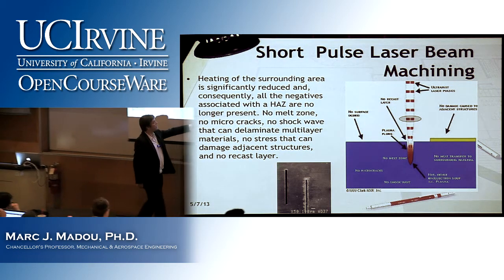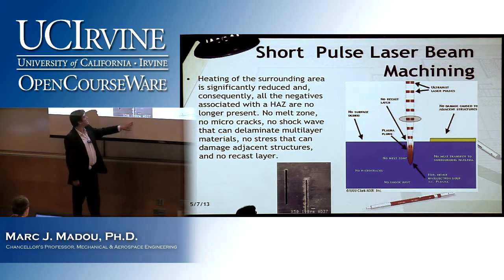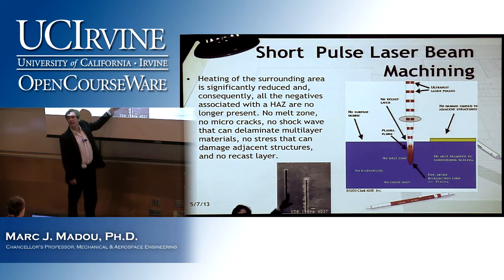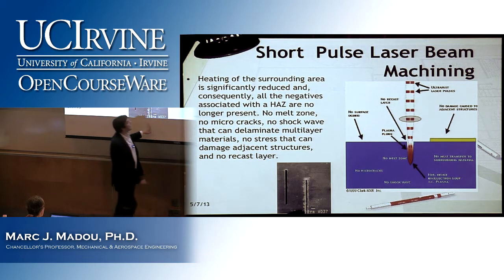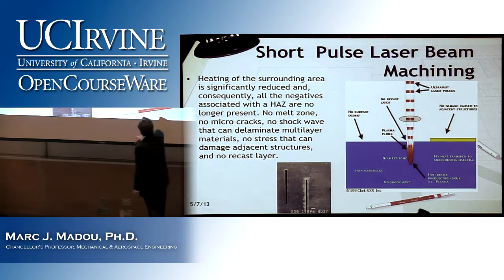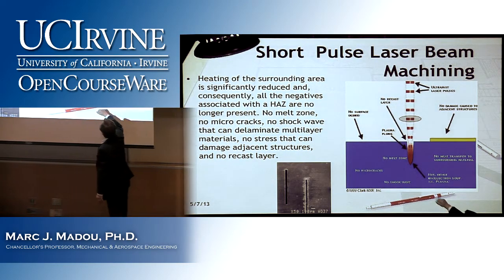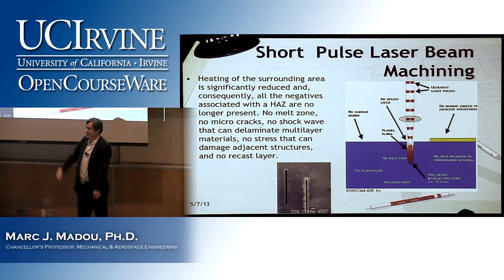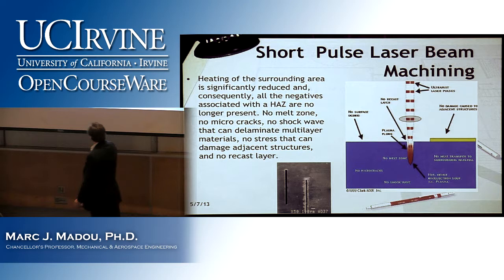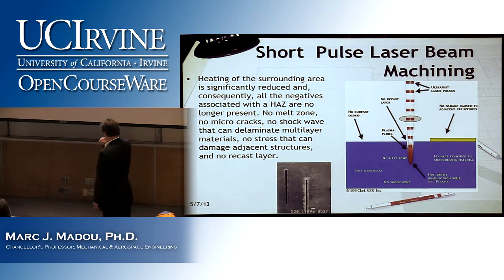And here you see the difference. So that's a cut with a traditional laser. This is a cut with an ultra-fast pulse, a femtosecond laser. And look at this, no melt zone, no microcracks, no shock wave. All the heat is applied where you want it to work. So a dramatic change in perspective for short laser pulse machining.